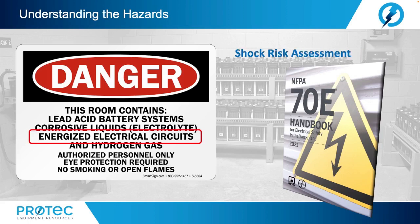Now, since we are going to be working around energized equipment, we still need to perform an activity hazard analysis, which could either be part of an energized electrical work permit or simply part of our job hazard analysis. Part of that is going to be performing a shock risk assessment. So, things that we will need to clarify: what is the voltage to which the personnel will be exposed?